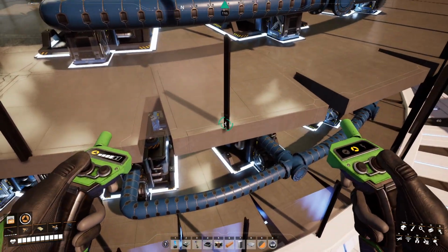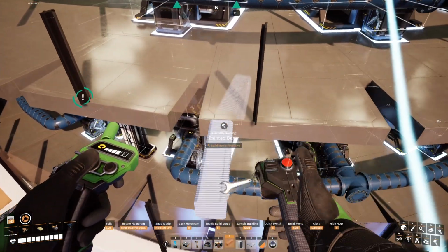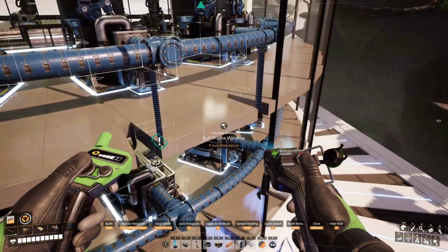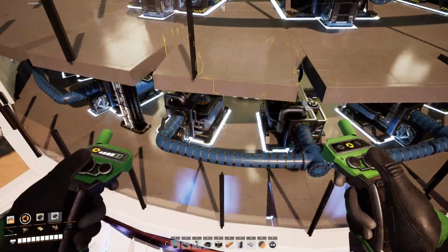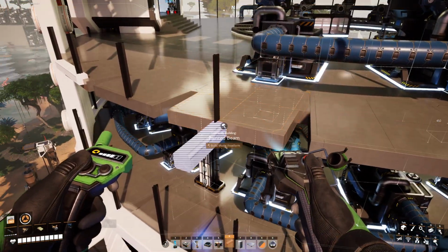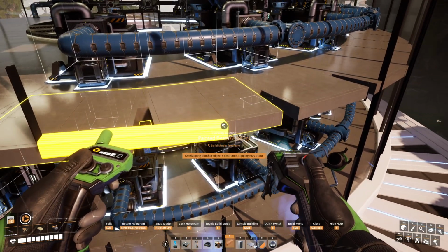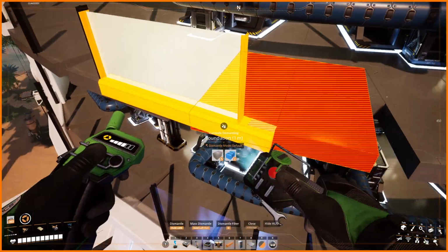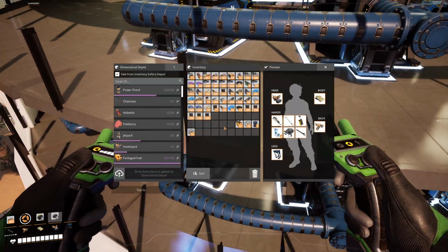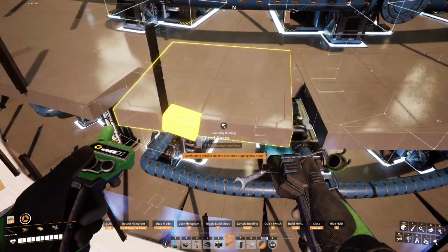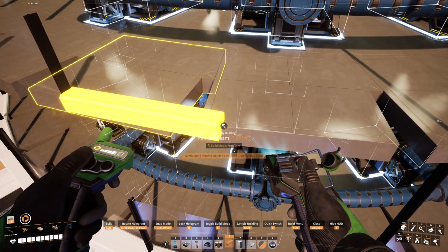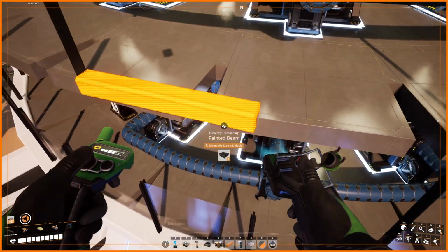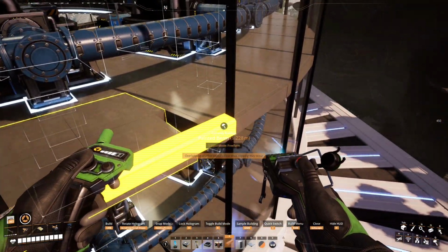So you'll see it's right on the edge every time, and this is the best way I could find to not be forced to use the gap. So to not be forced to go on the edge and then have a gap and then fill it with a pillar. Doing it this way actually makes it look quite good, and best practice would be to try to get it as close to 8 meters as you can. You won't always be able to do it, but that is the idea at least. So you can see there's 7.8, then it jumps to 8.8, so we're going to use that 8 and just put it down there, and we'll just basically continue like this.